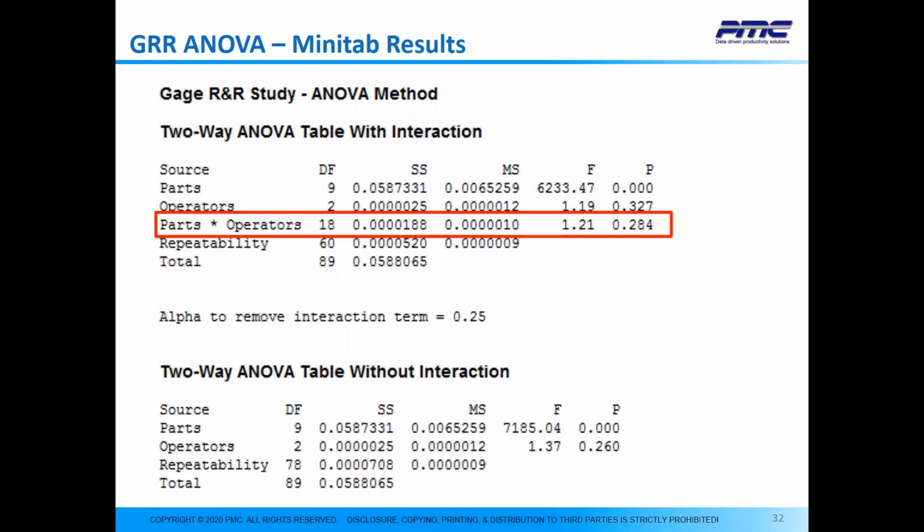For example, a press under heat may not be an issue, and the results may be the same, but when you add humidity, you may have electronic components that are very sensitive to humidity and heat at the same time. That's the interaction between the humidity and the temperature that we have to consider when we're conducting some of these studies.